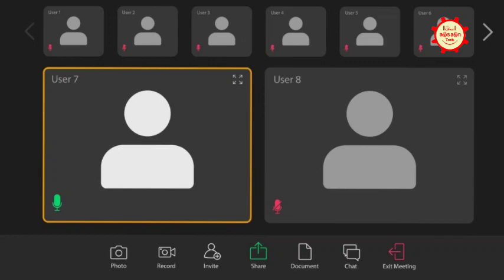Because if we consider only 20 mm and do not count the 15 mm thread, which will also be outside of the assembly, then in the calculation we will receive only a 5 mm gap. And in production, 5 mm is nothing. Then the floating flange and backing ring will slash and the assembly can't be completed. Okay, so we have to give them more gap.